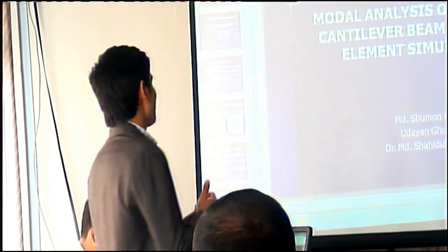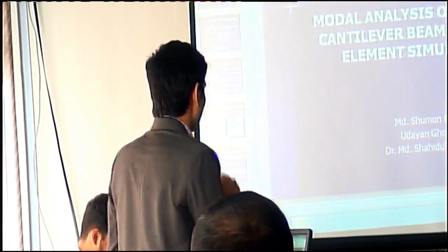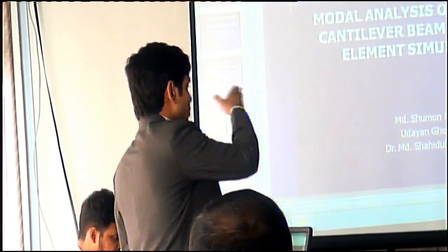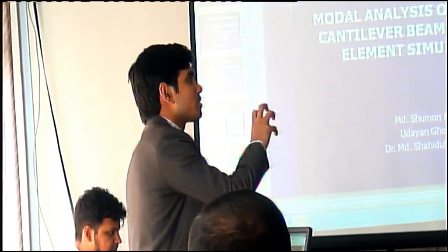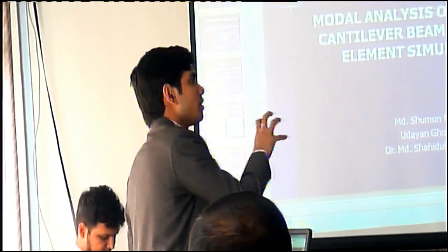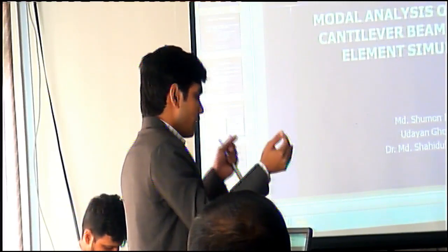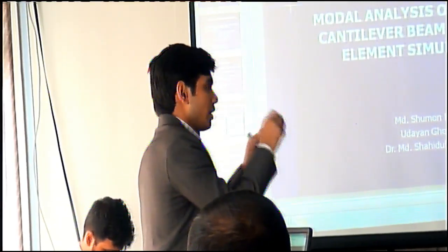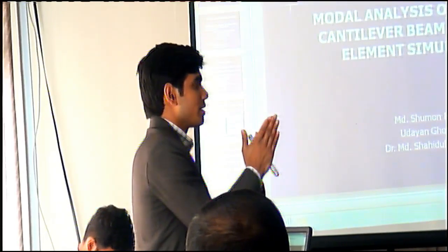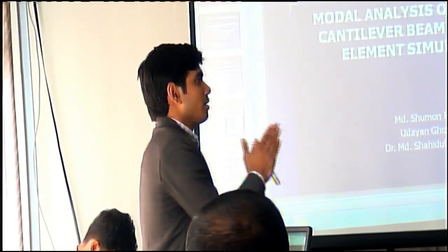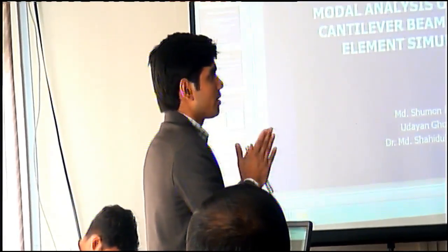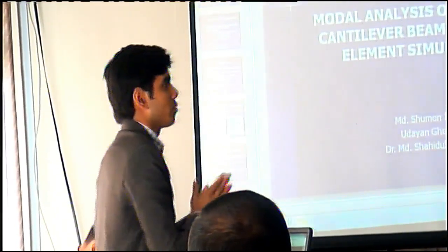Yes, these are interesting findings that I have shown in the visual representation. Here in the mode shape, a node is created in mode 3 just at the middle of the cracked beam. So the crack is contracted, a node is created, and it comes into contact. The opening is just contracted, so there is no crack present. It acts as a closed crack. Closed. It is closed. Okay.